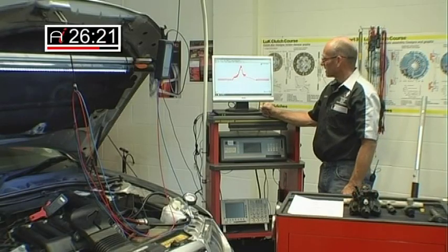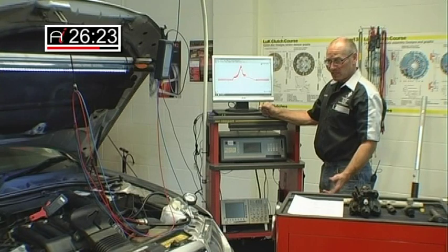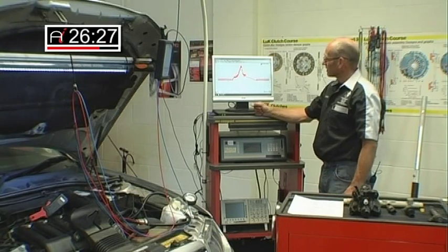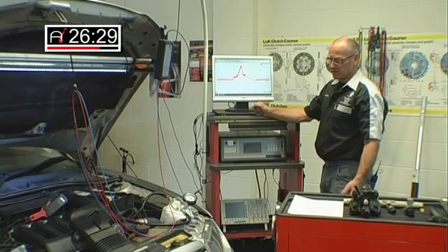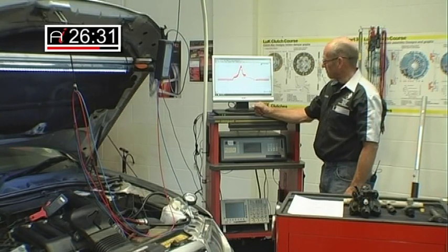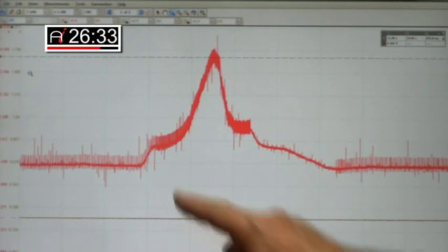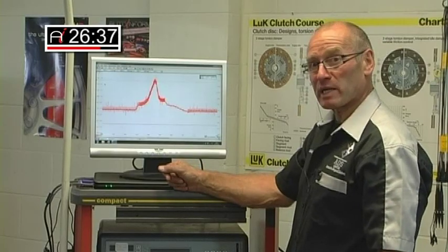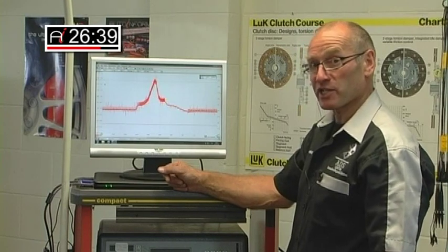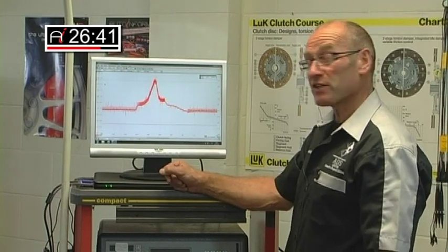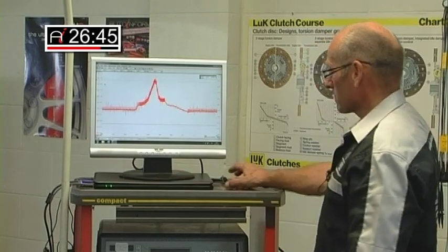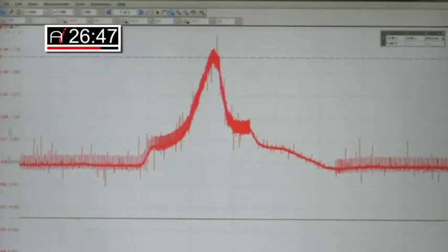over 4 volts. It's a 1350 bar system, 4 volts out of 4.5. 4.5 volts is maximum pressure. We're well above 1000 bar pressure. So once again, the rate of rise is very aggressive. We're well over 1000 bar or around 1000 bar pressure. So hydraulically, there's nothing wrong with this system. That further challenges priming, of course, because the whole pump has to work harder. And the rate of rise,